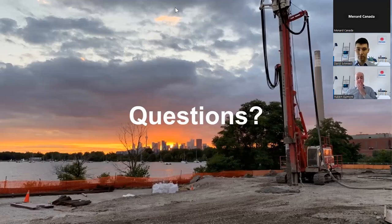Dynamic compaction, of course, is one of the most vibrating techniques, so it will cause some vibration. What we usually do is, we have a vast database giving us the vibrations as a function of distance from the impact point. We've monitored hundreds and hundreds of projects, so we have that database. It helps us when looking at distances where it can be suitable. And so yes, you need to be concerned.